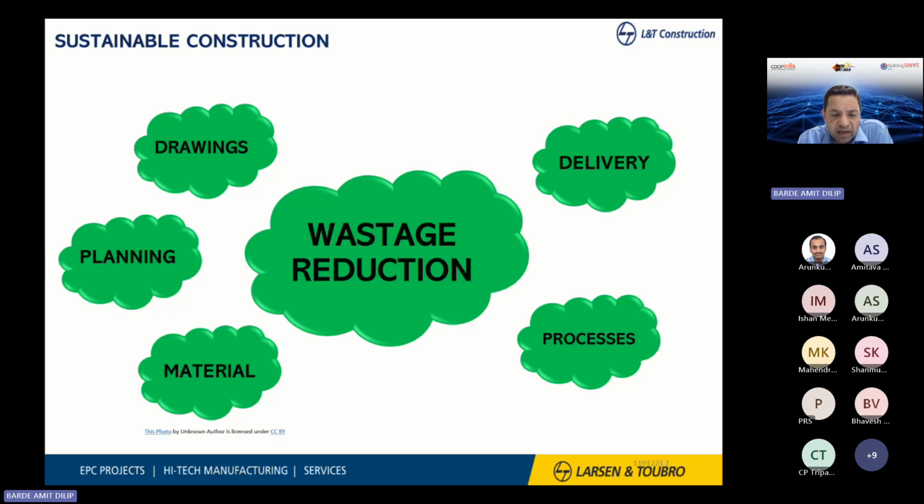And how we have done also, just one quick example and then I'll conclude. What we have done in the past is my steel wastage used to be about 3 to 4%, and that's a very standard norm. Sometimes it's even higher. But we have tracked now a 2 year long wastage of steel in the precast factory, and it came to about only 1.5% at the max, usually lower on average. In my ongoing tenders, we have started now, if it's a precast factory, steel wastage is 1%, right?